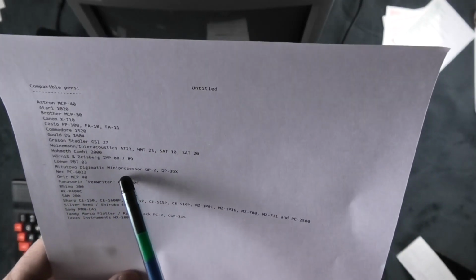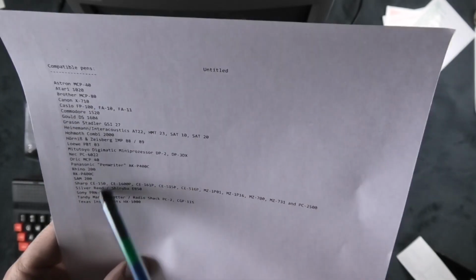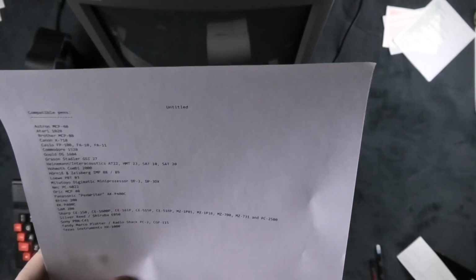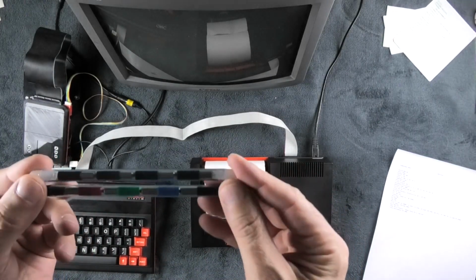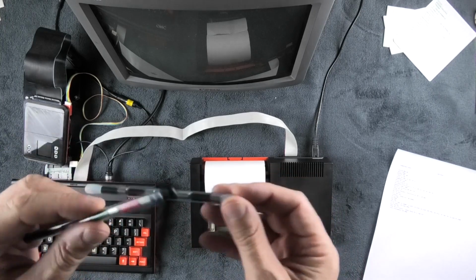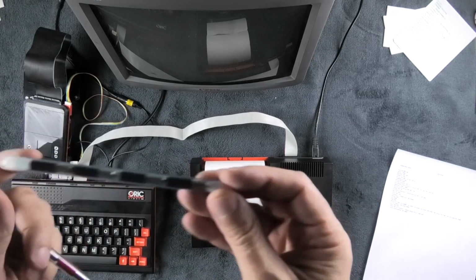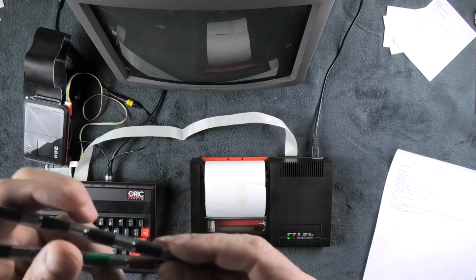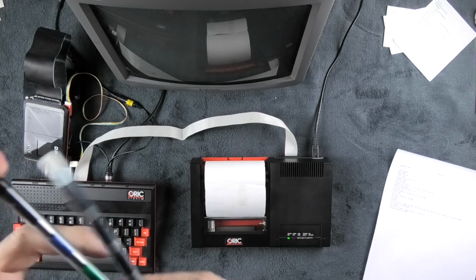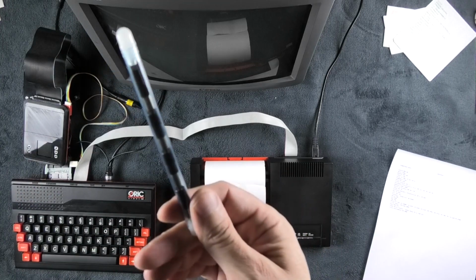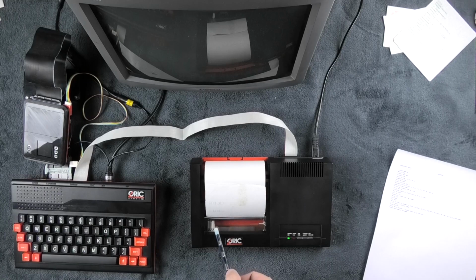Mitutoyo Digimatic Mini Processor, DP2 and DP3D, etc., etc. They all use similar types of pens. And you can often find two sets of four, some with four colors, and some with only black. So if you are going to do a lot of printing of just text, I recommend putting in four black pens, and when the printer starts to display a bit weak, you just switch the color select to go to the next set of pens.